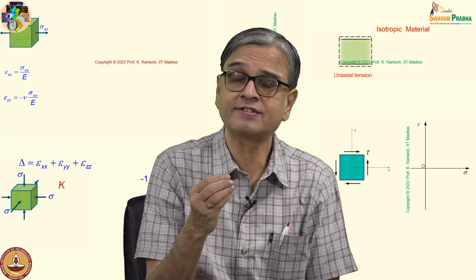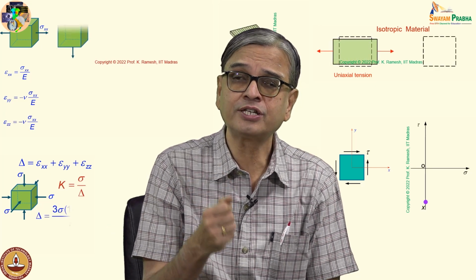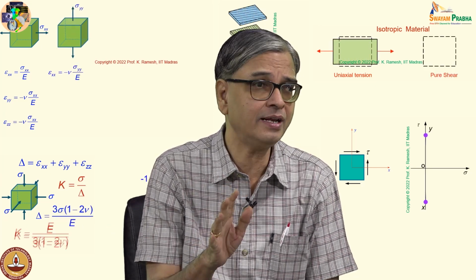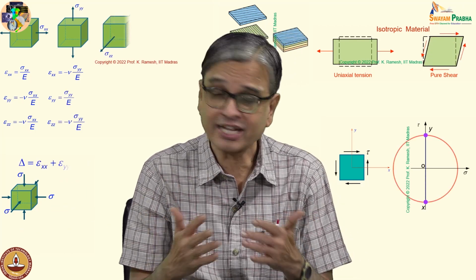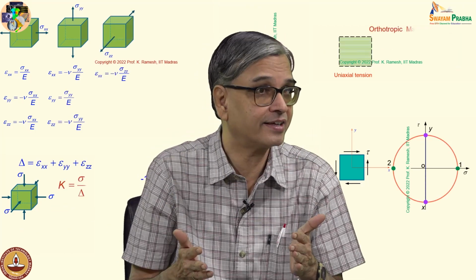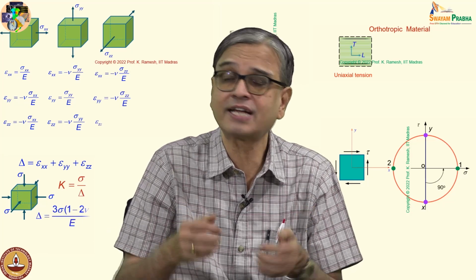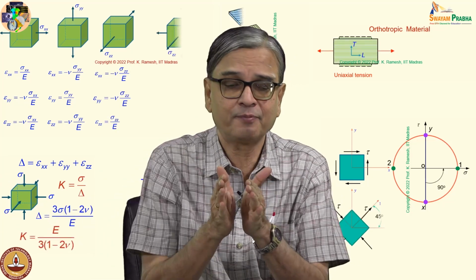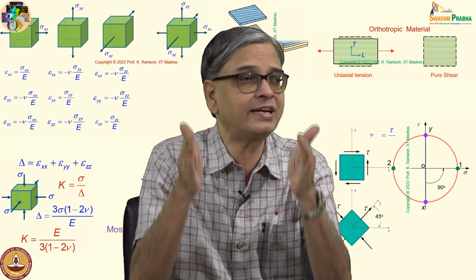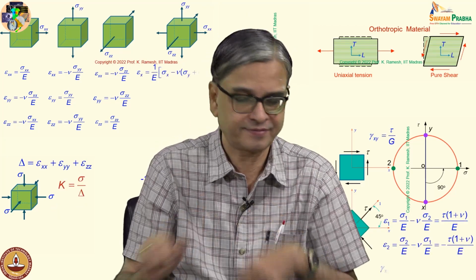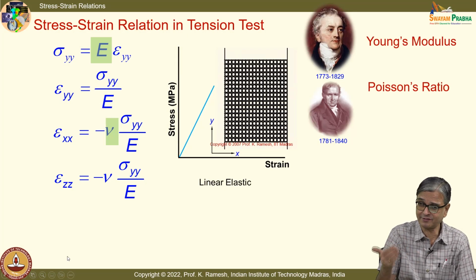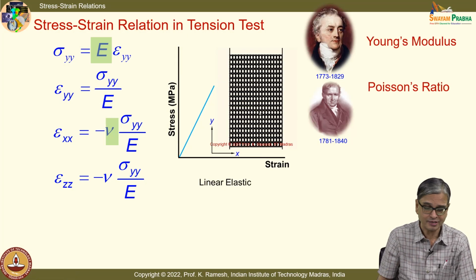See, while we discussed strain, I also said imposing uniaxial stress is very simple. Imposing uniaxial strain, I have to take extra effort to constrain, and for that I simply compressed, and bulging out I prevented by a rigid block, and you had uniaxial strain. But biaxial stress will be developed, that is a different issue.